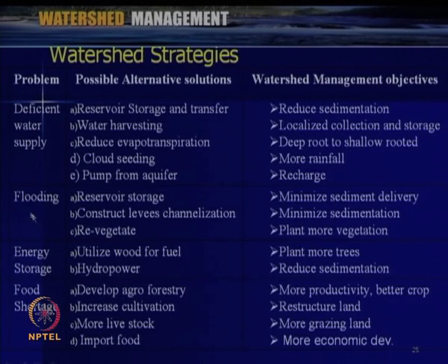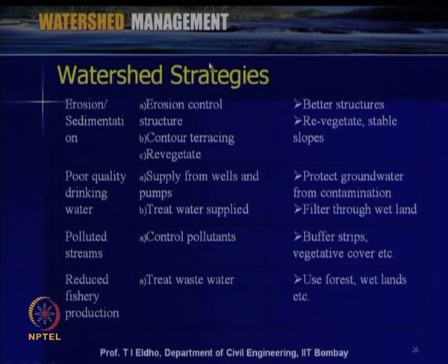If the problem is related to flooding, then we can use reservoir storage, revegetation, and construct levees, and to minimize sedimentation, plant more vegetation. Similarly, where energy is concerned, utilize wood for fuel, and hydropower. Where food shortage is concerned, develop agroforestry and increase cultivation. Like that, depending upon the area and the strategic plans, we can choose alternative solutions to deal with a particular problem.